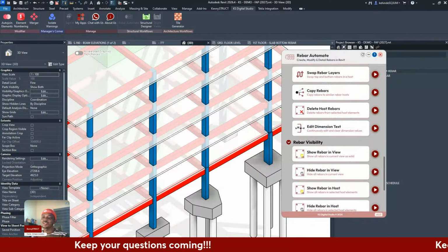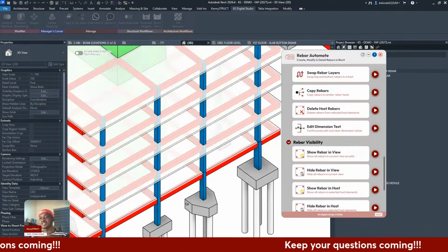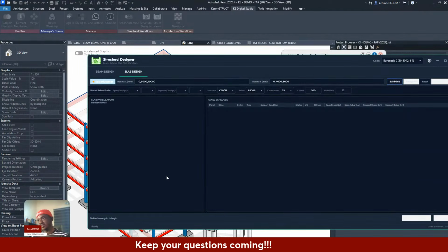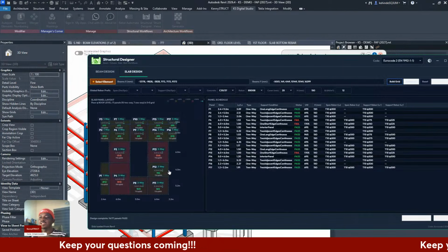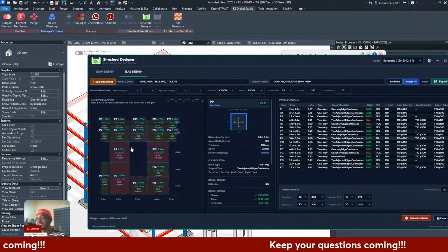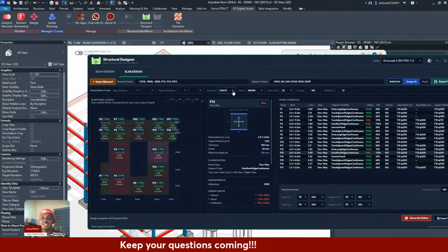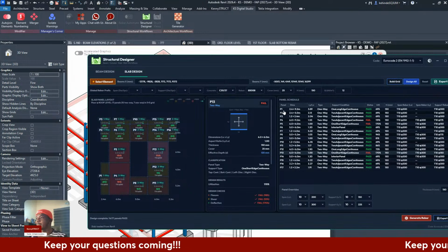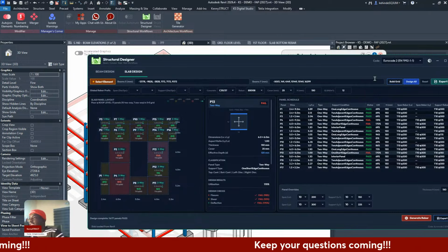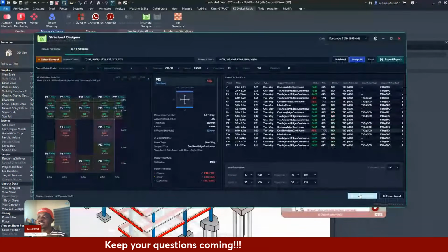It's a tool that also just selects your components. I can just pick any components here, any slab rather. So this slab, and gives me the layout of the slab and each of the panels on that slab, and then design all the panels individually, or just change certain parameters and design all of them at once, and tells you in real time which panel is failing, which panel is passing. And also generate the rebars inside of that panel, inside of the slab.